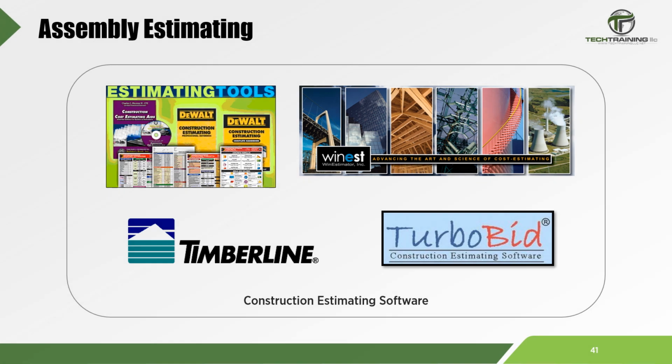Many high-end estimating computer programs allow the user to prepare detailed estimates by taking off assemblies. For the switch assembly, the estimator would take off the number of switch assemblies needed for the project, and the software would add one single gang box, one single pole, one cover plate, 2 wire nuts, and 20 feet of NMB 12-gauge wire to the detailed estimate for each switch assembly.